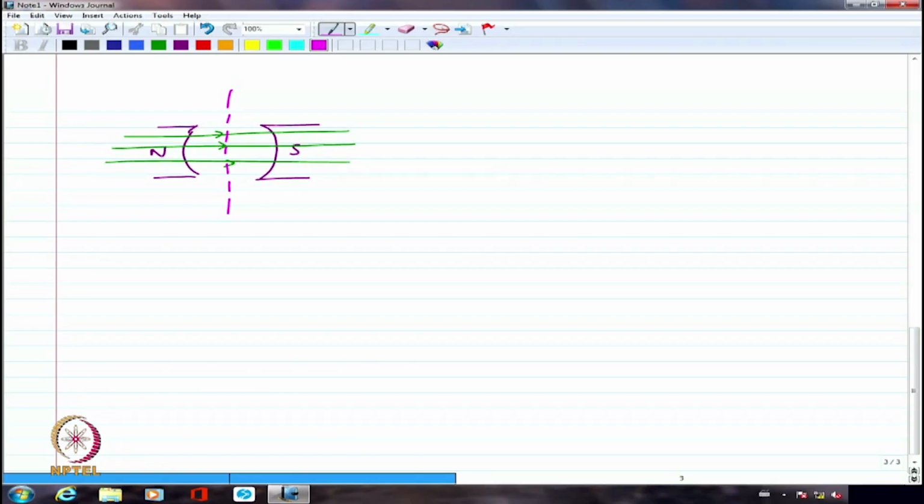So when it is drifting, obviously it will go through a zero. The current will go through zero. And when it is going through a zero, it is always easier to change over. So that's the reason why we are placing the brushes somewhere here. So the brushes are normally placed along this axis, which is perpendicular to the magnetic axis. So we call this the neutral axis.